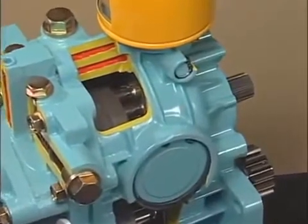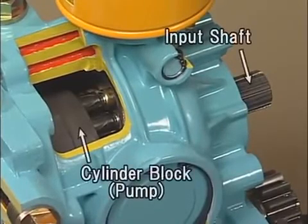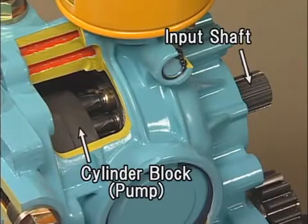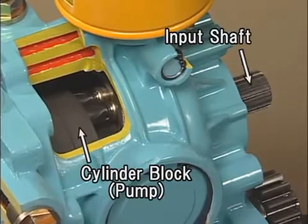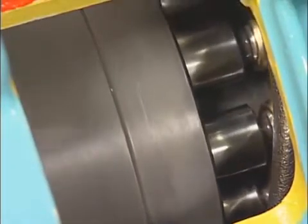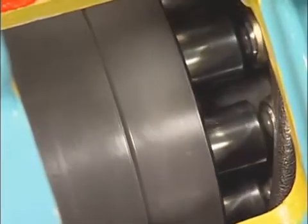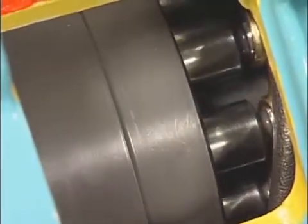Now let's look at the pump mechanism. Here on the pump side is what we call the cylinder block. The input shaft and the cylinder block are connected by a spline, so if the input shaft turns, the cylinder block also rotates. In the cylinder block, an odd number of pistons are arranged to reduce the discharge pulsation of the hydraulic oil. This HST has 9 pistons.